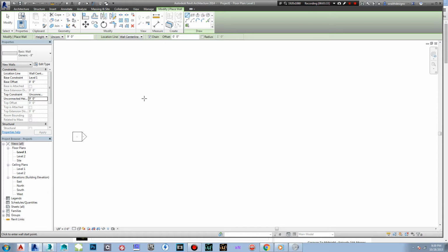So here we go. Right now I'm just painting the 2D version of the walls. I did it in feet as well, so I'll zoom in here so you can see it. We'll just start off. This snaps, as you can see. It's not completely free. You can make it free if you want, but I wouldn't advise it. It also shows you radius. You can zoom it around, all that stuff, so you know what's going on. You'll get the measurements as you do it. So we're going to go to a 15-foot wall.